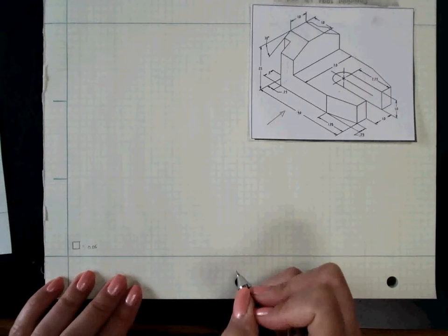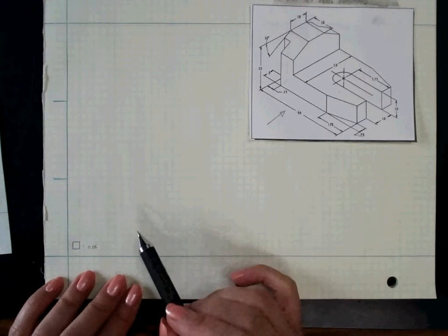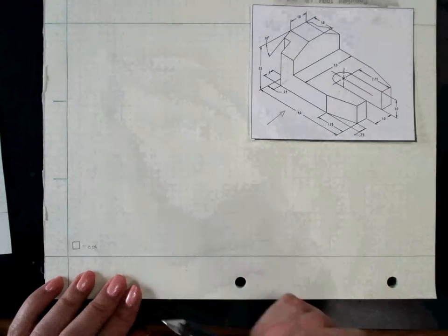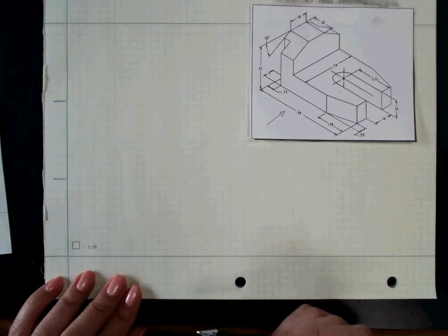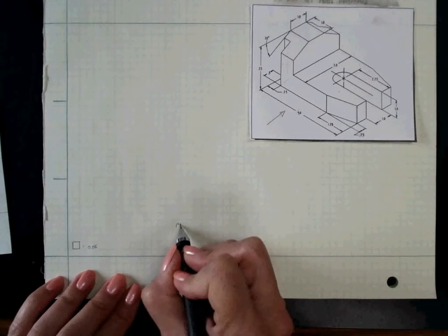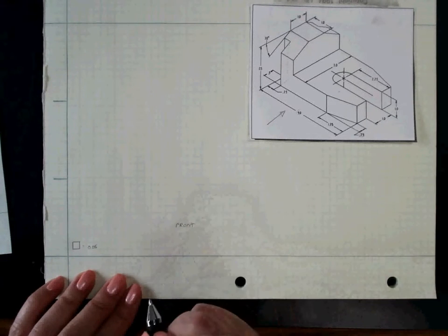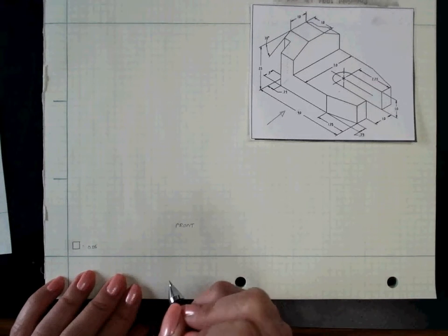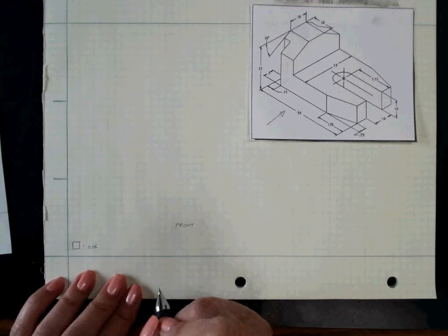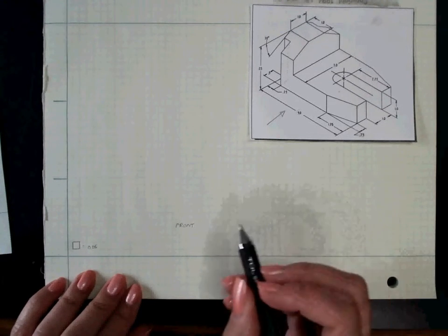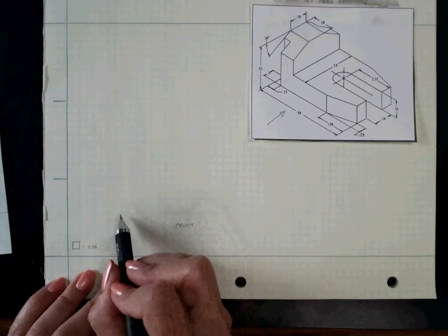Now, before I made that decision, I also did a quick check to make sure that I could fit a front, a side, and a top plan on here, and I can. So we're going to go ahead and get started. We're going to start with the front, which, if we're doing third angle projection, remember, goes right down here. And before I draw anything really, I'm just going to double check my assertion that everything will fit by sketching in rough rectangles of the space I'm going to require for each of these views. And I'm going to do this very lightly because I'm going to end up erasing a lot of this.